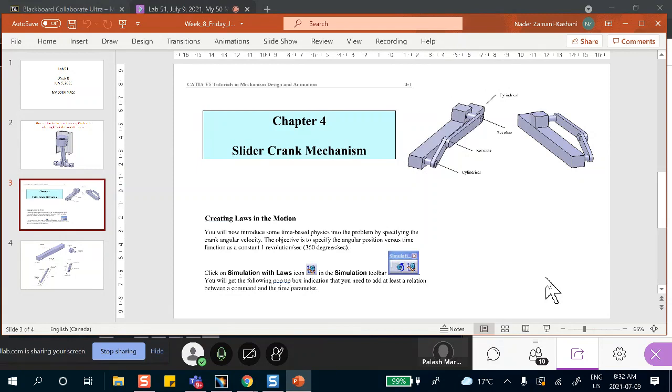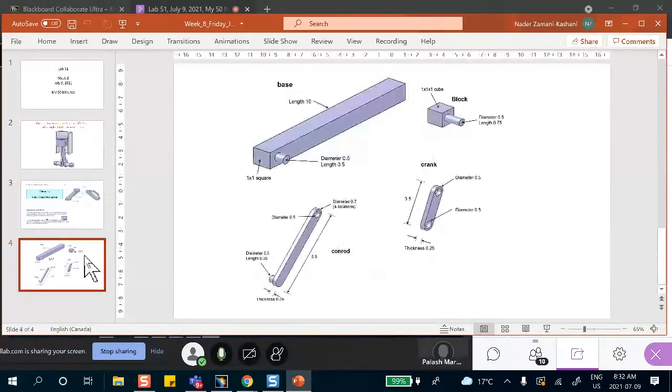All right. Now, I have taken some dimensions here just for the sake of illustration. They don't have to be like that. Obviously, if the crank radius is different and the connecting rod is different as far as the size goes, then the accelerations will be different. However, the size of this block has nothing to do with the acceleration, or the size of the track has nothing to do with the acceleration.